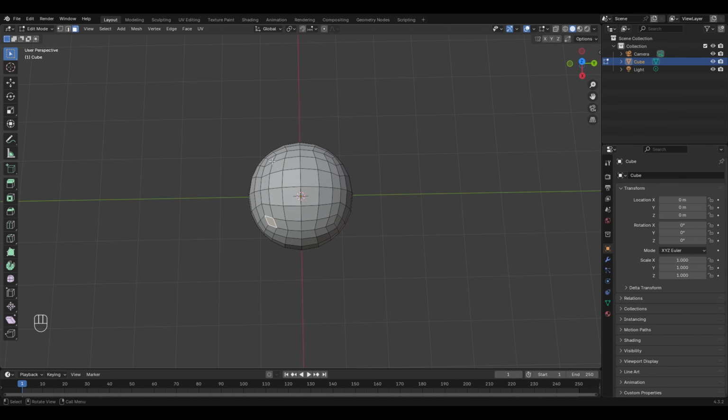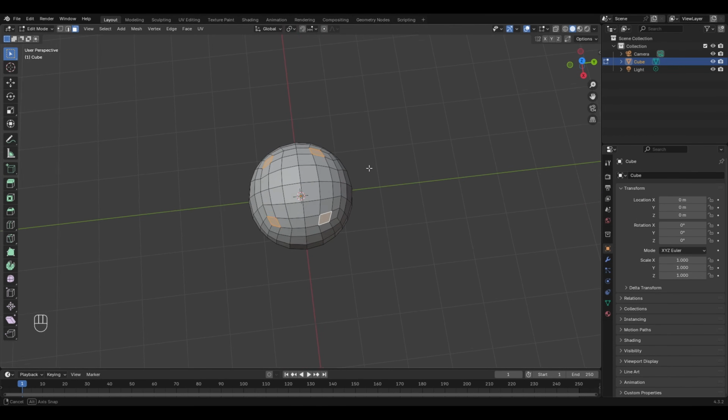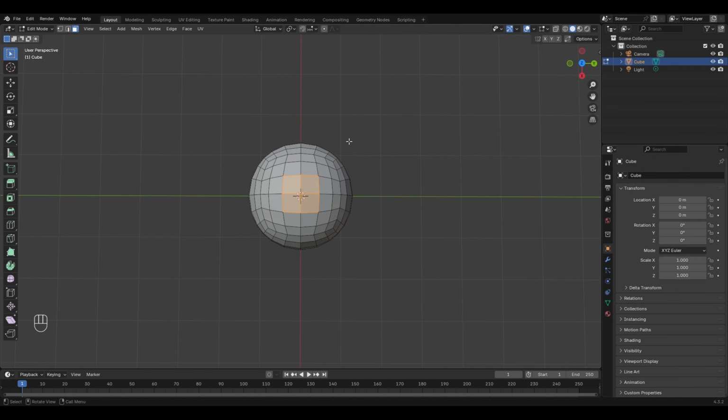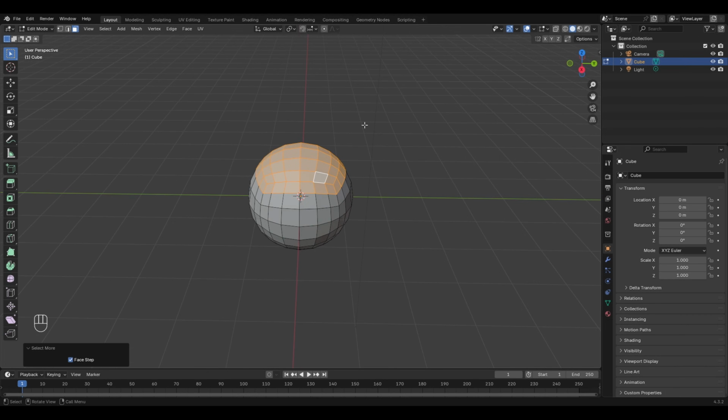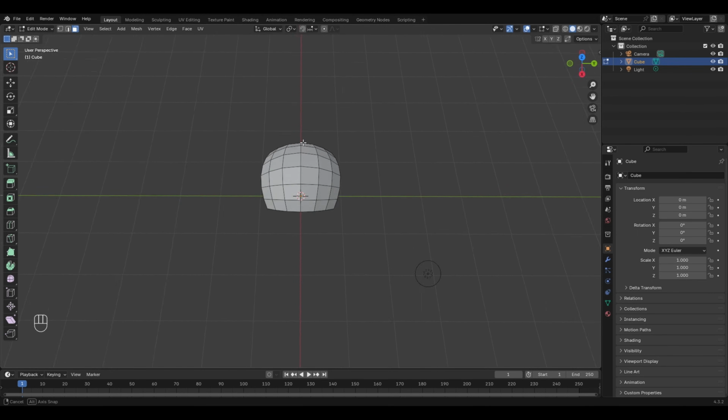This is the top side of the box. We can see the corner of our box. We will take this one side and remove the others. Let's select this top side, select the middle one. Now expand the selection by pressing Ctrl plus, and again. Now select the inverse. To select inverse, press Ctrl I and let's remove this by pressing X and select the vertices. Now we have the top side.